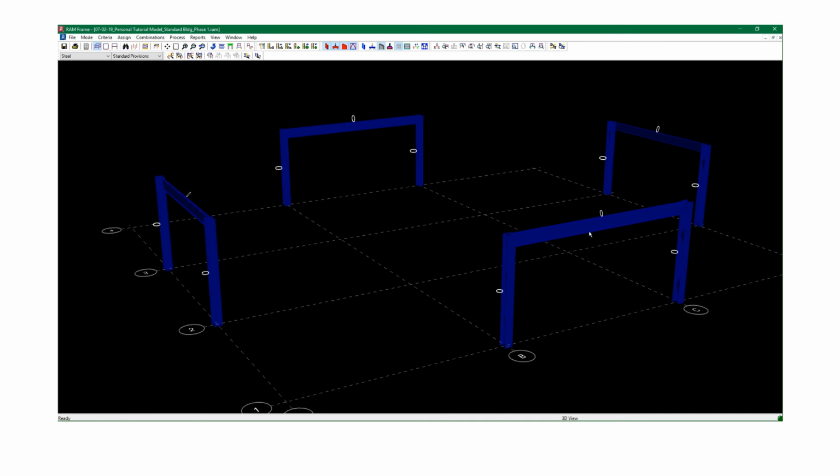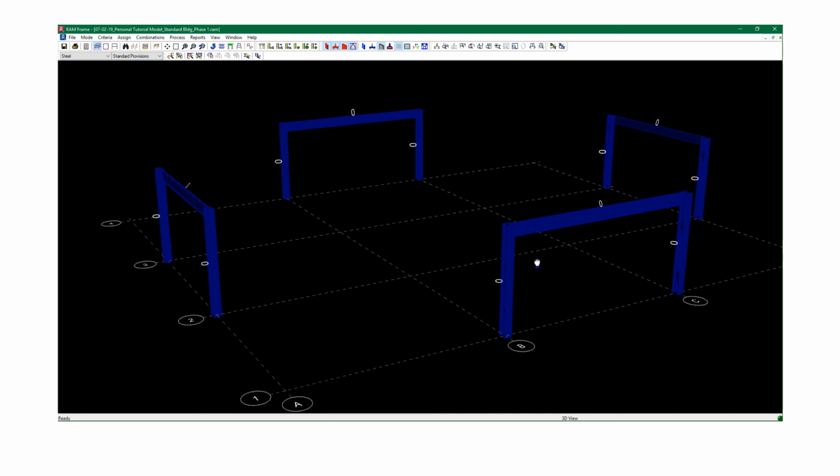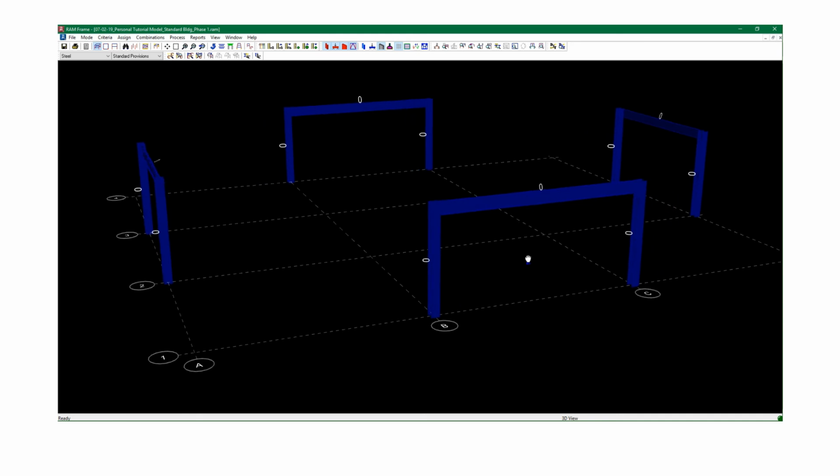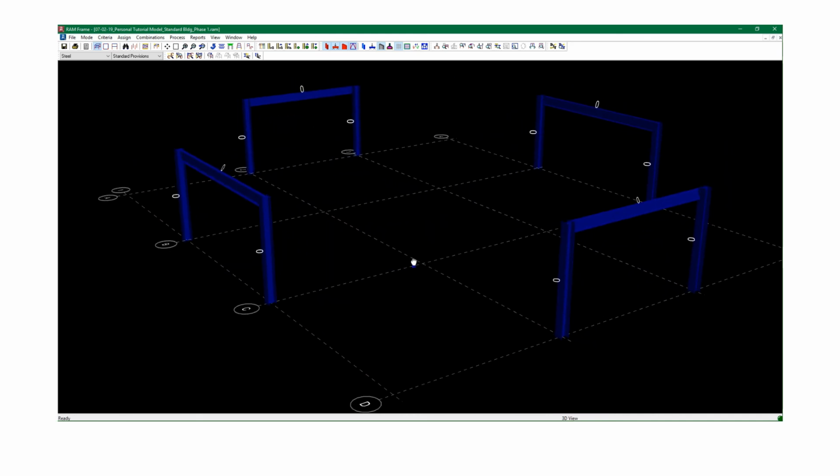Well, through the cladding. And the cladding, if it's attached to the underside of the beam or the side of the beam somehow, you're going to have some local effects if the deck is considered not to be bracing the structure, for example, and that load doesn't go directly into the diaphragm. So that's one issue. Another thing is the same thing could be happening here with the columns. It could be wind load that's actually tributary to these columns from girts, and you need to investigate that, or any type of local bending that occurs.